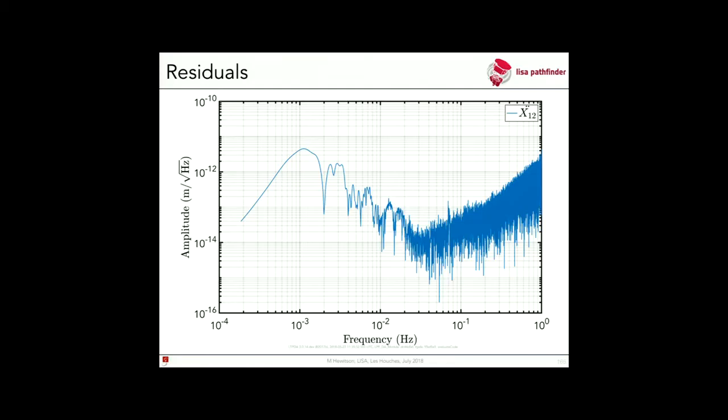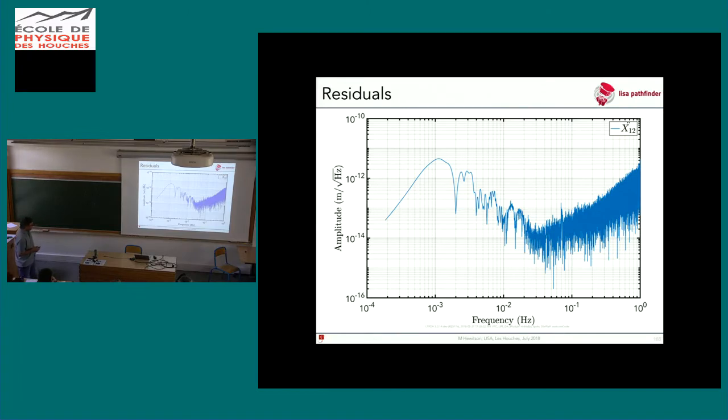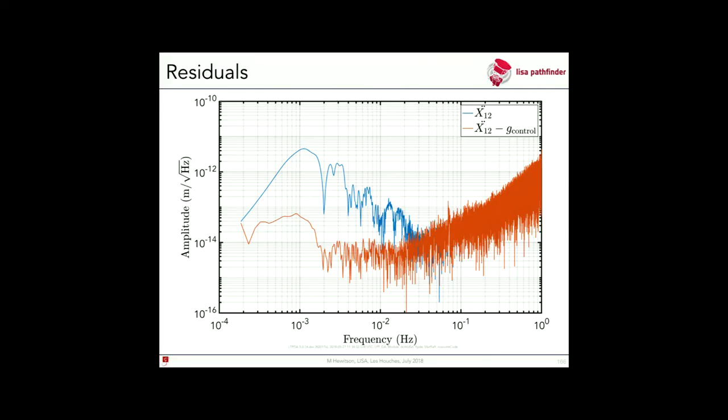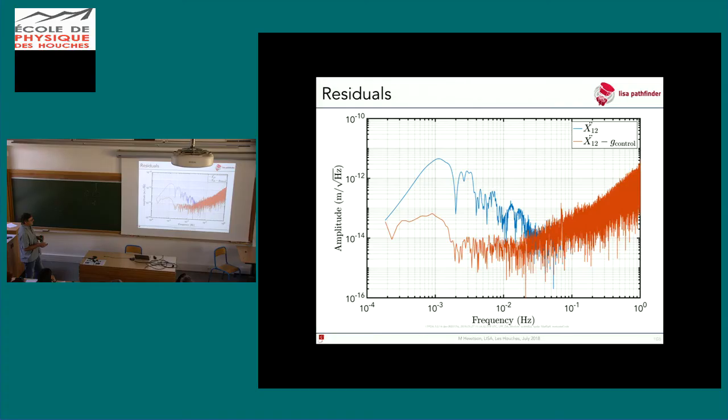And once I get those two things to agree, all of my injected signal goes away, and I'm left with the residual noise. This is the observation in the frequency domain. It doesn't make too much sense in principle to look at frequency domain for an injected sinusoid, but it gives a sense of what's going on. So all of that is signal power coming from the injections we made. If we account for our best estimate of the control forces, we subtract quite a significant amount of that. So in removing that noise power, we've tuned the parameters of this control force. We've calibrated the gain. I can do the same for another parameter here, and you see there's very little difference. So we're not very sensitive to the parameter involved in that force gradient.